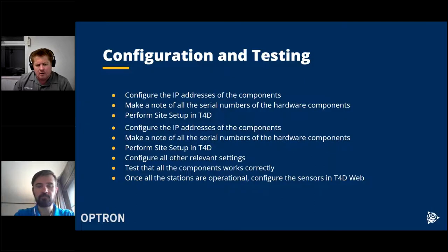Sometimes when you receive the coordinates for the orientation beacons from the client, it might have been measured using GPS and not total station, for instance. So when you do the site setup and you have a look at your residuals of that orientation network, you will find sometimes that you will have a couple of outliers.